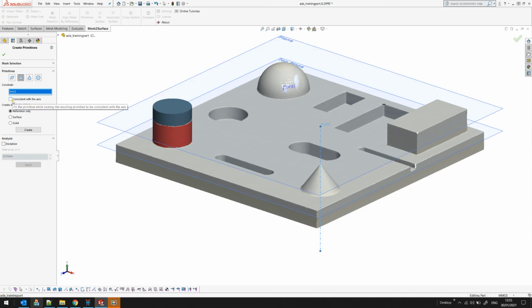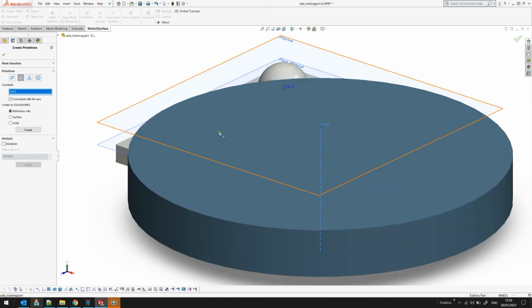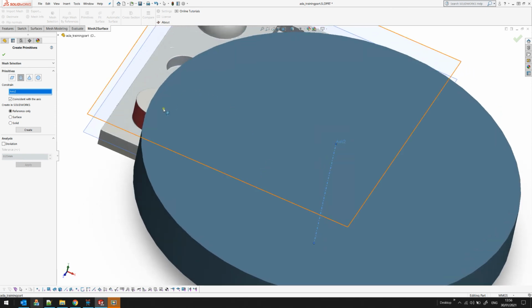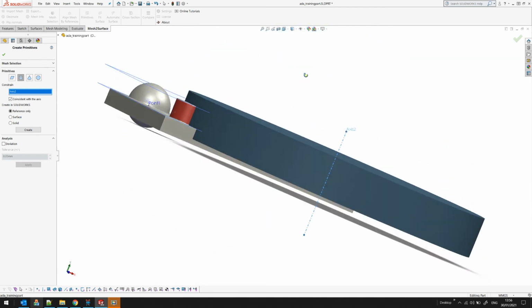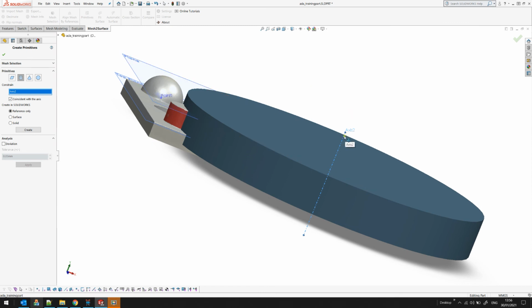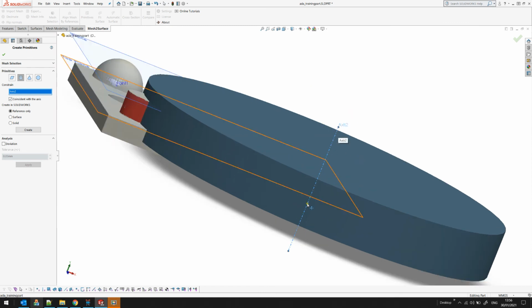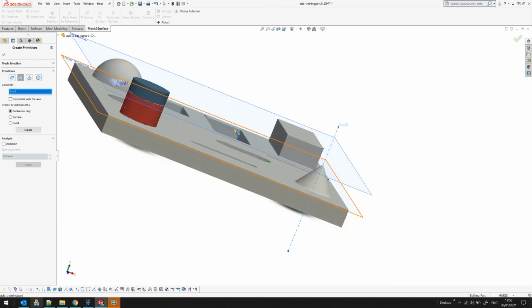There is a checkbox here, which you may need in other examples when you have two coincident cylinders or cones. In this case, you tell the software to do its best to fit through the points, but that you want your axis to be coincident with the given axis. In these examples that doesn't give the expected results, but everything is correct because it complies with the constraints. It goes through this axis, but at the same time it fits the selected points, and that's why we get this result. So this is not the case for me.